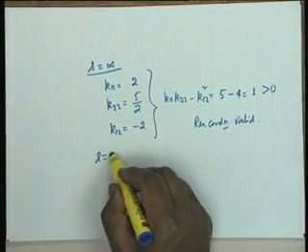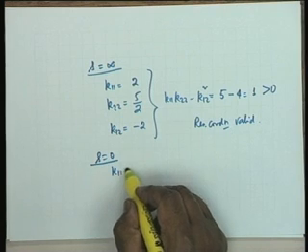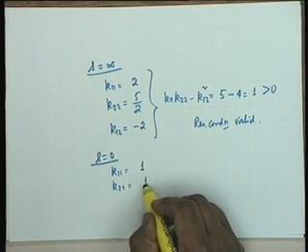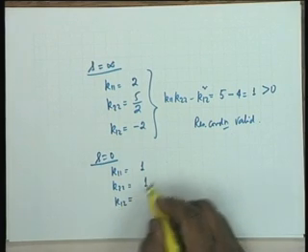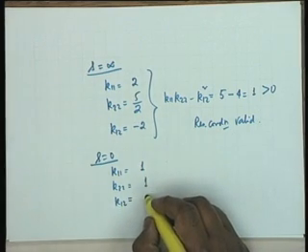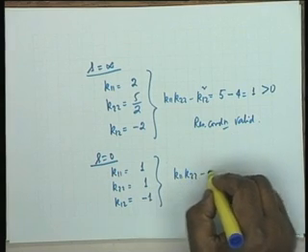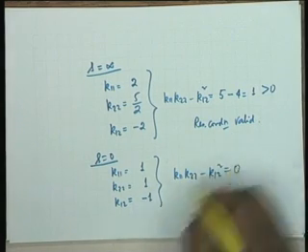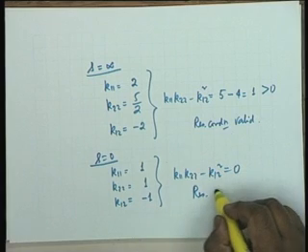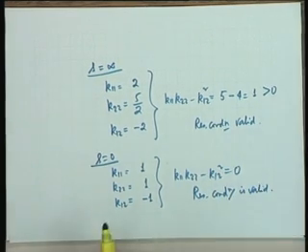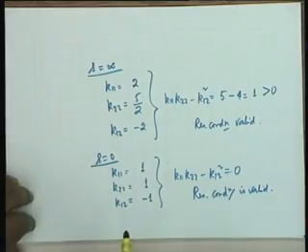For the pole at the origin, k11 is 1, k22 is 1, and k12 is also equal to minus 1. Therefore, k11 k22 minus k12 squared is equal to 0. Again, residue condition is valid. Okay. The B part. Any question on this?